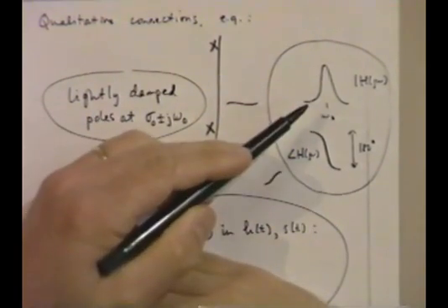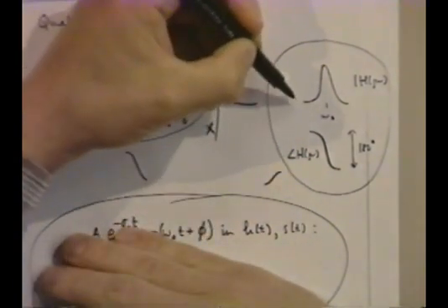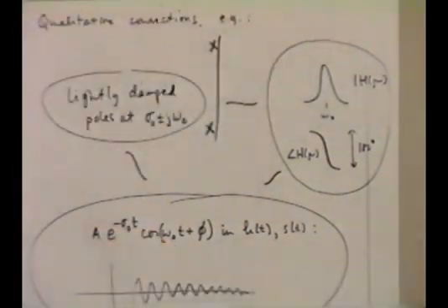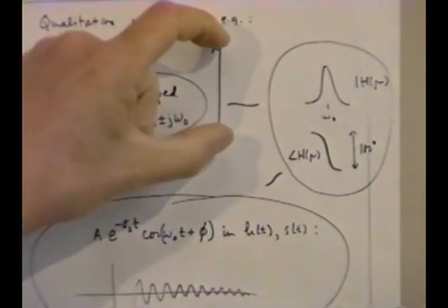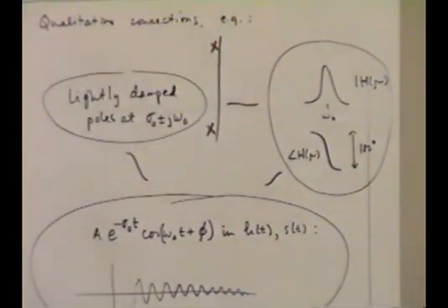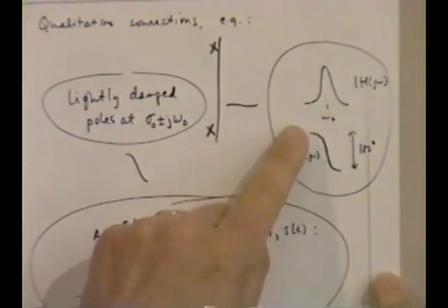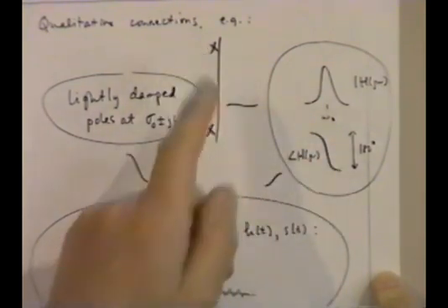For example, on a Bode plot, on the magnitude plot, you should expect a big peak in the frequency response. And that makes perfect sense. What it says is if you feed a sinusoid into that system near these frequencies, you're going to have a very big response at the output. You should also realize that this means there'll be a rapid phase shift near that frequency.